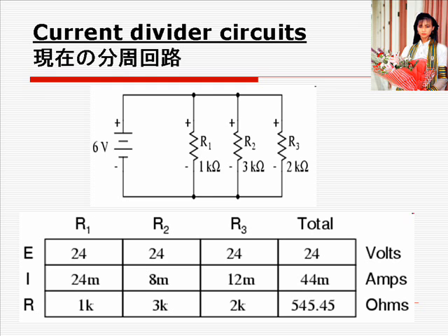Knowing that branch currents add up in parallel circuits to equal the total current, we can arrive at total current by summing 6 mA, 2 mA, and 3 mA. The final step, of course, is to figure total resistance. This can be done with Ohm's law, R = E/I, in the total column, or with the parallel resistance formula from individual resistances. Either way, we'll get the same answer.